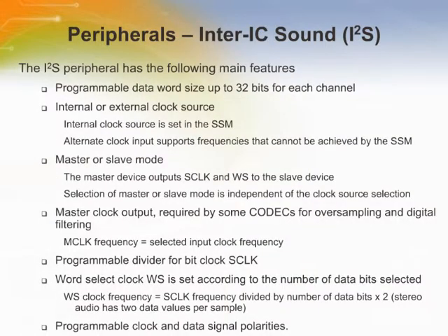The I2S interface, or Inter-IC Sound Standard, was developed by Philips Semiconductor to provide a simple, low pin count serial link for digital audio data. I2S is a synchronous serial protocol for sending and receiving digital audio data in stereo PCM format. The eCOG1X I2S peripheral provides both master and slave capability, programmable data size and clock frequencies, and simultaneous bidirectional data transfers.